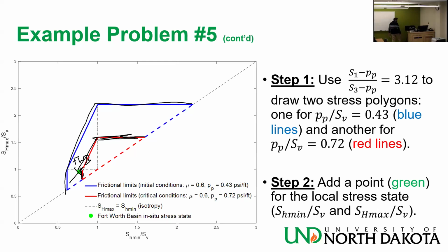Now, if I was using a Mohr-Coulomb circle, how would it look? On a sigma n, tau plot, my envelope starts from the origin, because I'm assuming that the rock is pre-fractured. We are dealing with large-scale rock, so I cannot have an intercept.